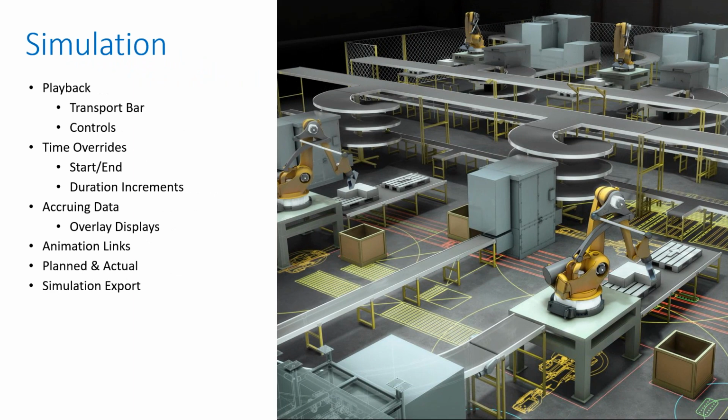So Horatio asked the question, if the tasks were imported from an MS Project file, is the percent complete from that file also imported to Navisworks? No. The only thing that it will show is the length of the task. Unfortunately, it doesn't import the progress. The progress in Timeliner is purely to give you an idea. It doesn't actually affect functionality in any way in terms of how we simulate the schedule later on.